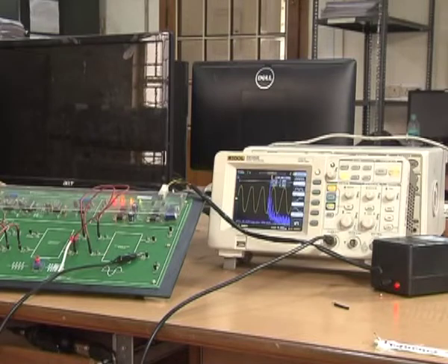In this session we are going to see how to modulate and demodulate frequency modulated signals. Frequency modulation, as it implies, means we change the frequency of the carrier signal with respect to the amplitude of the message signal. Now, the information is carried over the frequency, hence there will not be any amplitude changes. The frequency of the carrier signal is what changes.